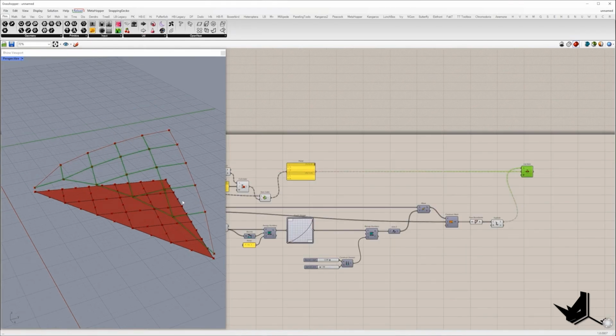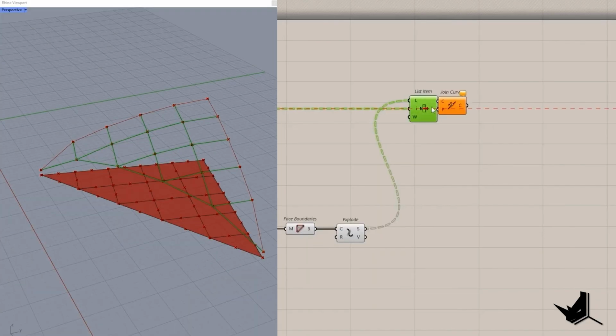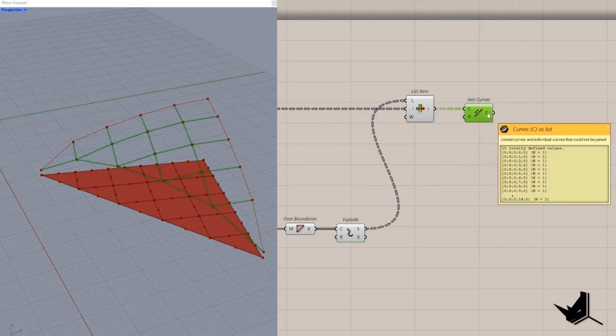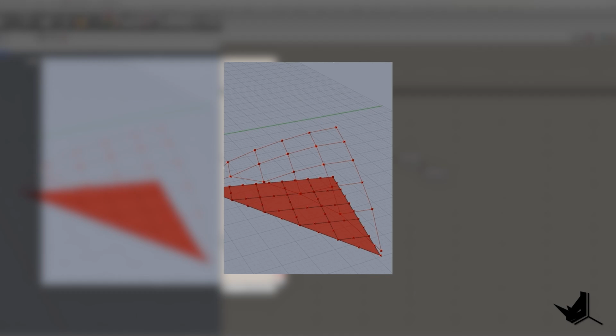All right, we have straight lines from each element, but we also need to create catenary curves. I'm going to join the segments. Inside each branch we are going to have a single polyline. I will extract endpoints. So let's say for this element here we have this polyline. I'm going to extract endpoints, and I'm going to create a catenary curve between these endpoints and the control points of the polyline which is closer to the attractor point, and it will look like this.